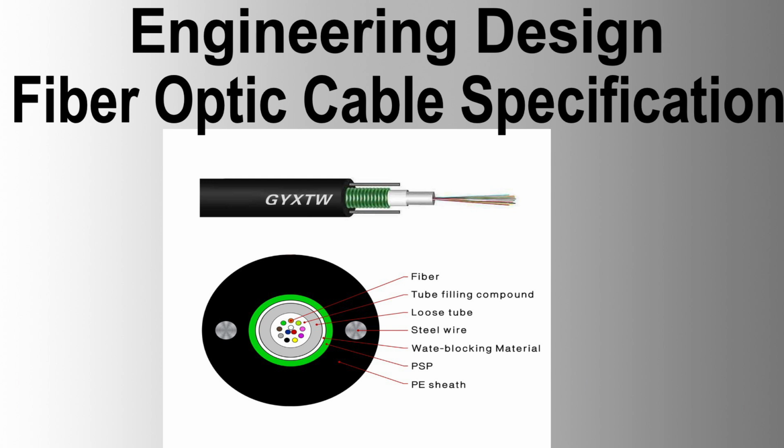Mandatory slack. Slack for future movements. Provide sufficient slack for future cable movements wherever the FOC is spliced or terminated. At block valve stations or splicing boxes, coil 10 meters of slack on each cable section. Inside racks, route the cable up to the ceiling and back down before terminating, tying it orderly to the rack. Trench laying. Allow sufficient slack to account for normal soil movements without putting unnecessary stress on the cable.